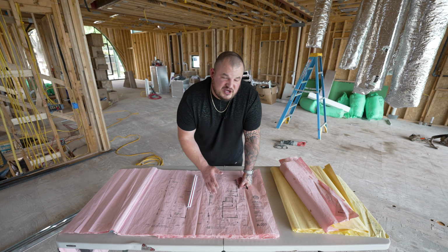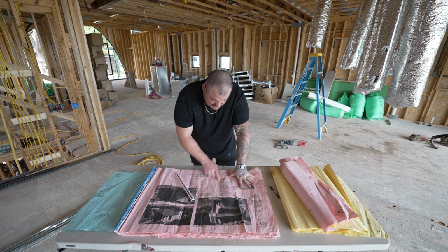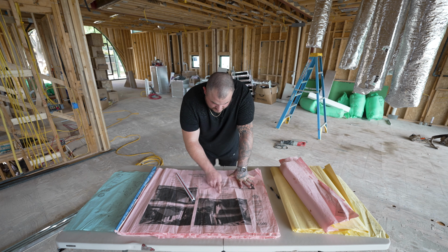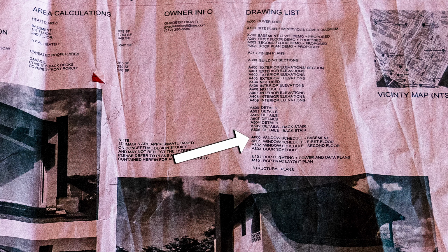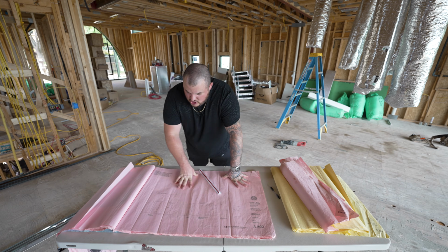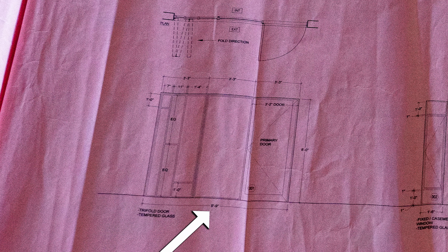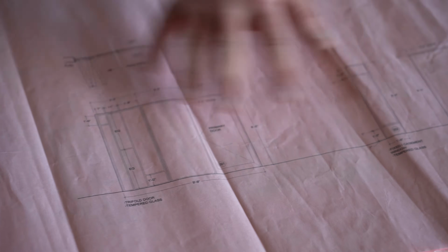Okay, let's go over to the window and door schedule so I can show you how that looks. So we go back to our table of contents. We go down here. All these pages are numbered. The window schedule and door schedule is from page A800 to A803. So let's go to A800. Here we go. We have some windows and doors. These are custom steel units. It's telling us what the whole frame size is, width 9 feet 9 inches by 8 feet tall. It also has a door in there that's labeled on the door schedule. So sometimes doors are integrated inside windows. But if you come over, these are more specialty.